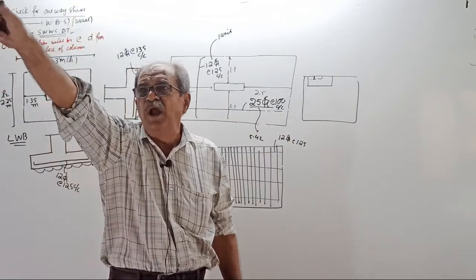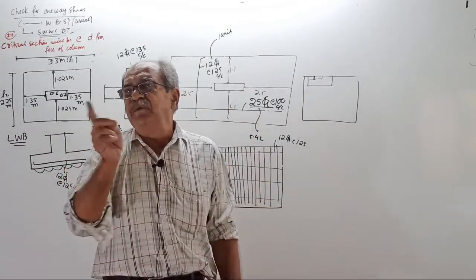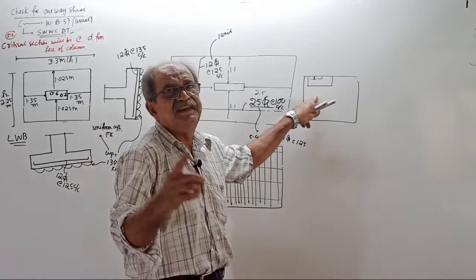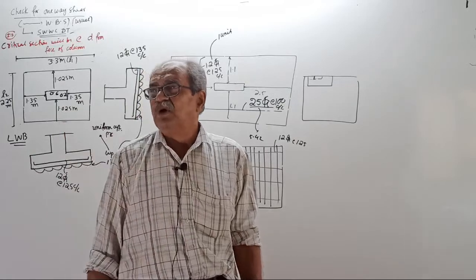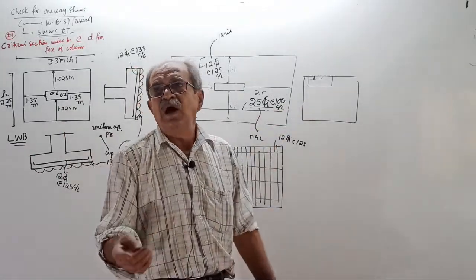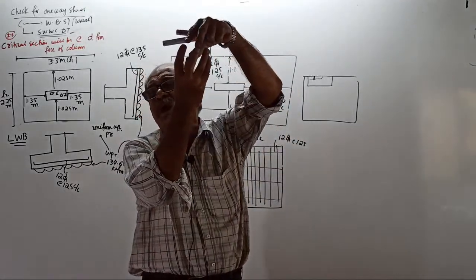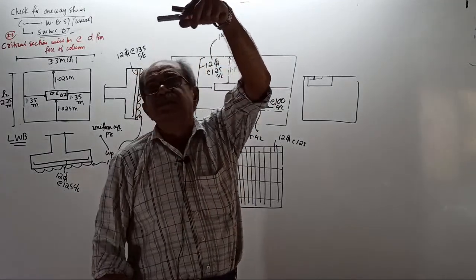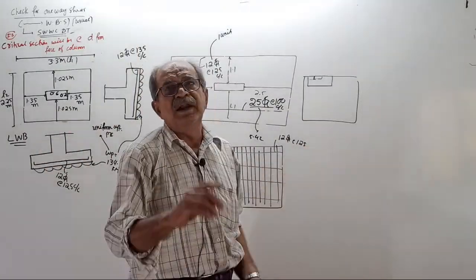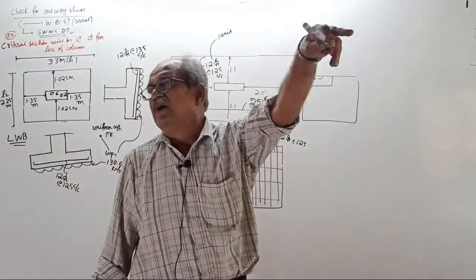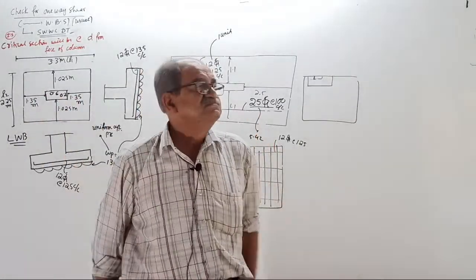100% that building, I know it. These columns and footings are useless. If you cut the footing, nothing will happen to the building because the existing footing is as good as cut. But why is the building still there? Because when the column cannot take the load, as the footing cannot transfer the load, that column will not be a compression member. It will simply be a hanging member. That joint where beam and column are there is just a hanging member. So the load will get redistributed and go to other columns. And because of the high factor of safety, the building is somewhat standing, but dangerous.